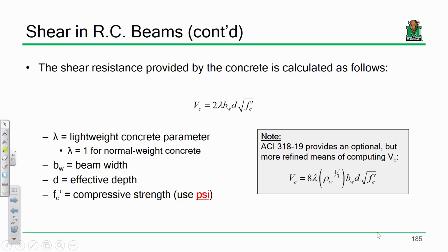Again, I'm not going to make you memorize this for an exam or anything. Don't worry. I just want you to have an understanding as to why that gray box is there. It would stand to reason that if I had a beam and I doubled its depth, that I would double its capacity, right? That would make sense. It actually doesn't work out that way. When concrete beams get really, really deep, their capacity doesn't double. It actually sort of peters off a bit. When you have really deep sections, their behavior gets a little wonky.